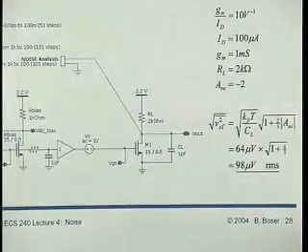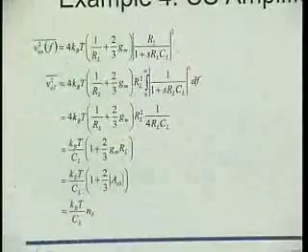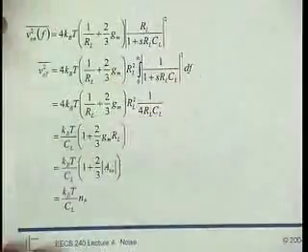That's the capacitor that the A to D uses to hold the signal. So now it's exactly the same noise calculation I had before, except that now I have to integrate that noise from 0 to infinity, and in a little bit verbose way, I've put the result here.